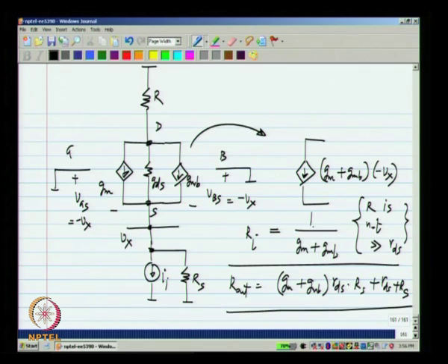okay. So, you can see that in this particular case, the body effect GMB is actually helping you. GMB is an additional control source in parallel with Gm, and it simply adds up to Gm in case of a common gate amplifier. It further lowers the input resistance and further increases the output resistance. And as you know, a current buffer is supposed to have a low input resistance and a high output resistance, and the bulk transconductance GMB actually helps you in this direction. Okay. Thank you. In the next lecture, we will look at the effect of body effect on the common drain amplifier or the source follower, and also look at other transistor level circuits such as the differential pair with which we can make op amps.